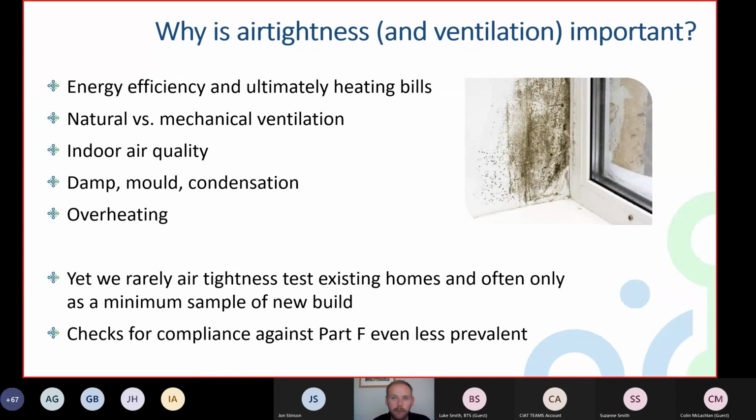when you have poor air tightness, it's usually not designed in. It's due to maybe construction defects or designs that don't quite work in practice. And that means that the fresh air provision is randomly dispersed around the house instead of being provided to where it needs to be. So it's much more important that we have a deliberate level of air tightness that we're trying to meet, and then providing the fresh air with ventilation. So the key is that they go together, air tightness and ventilation.